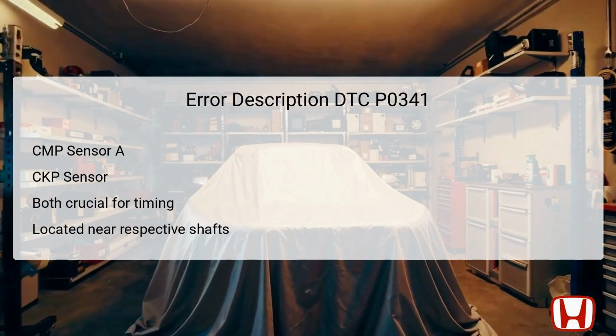When these sensors detect misalignment in their readings, it triggers DTC P0341, indicating a mismatch that can cause performance issues, irregular idling, or engine misfires. Therefore, understanding the positions and functions of these components is crucial for effective troubleshooting.